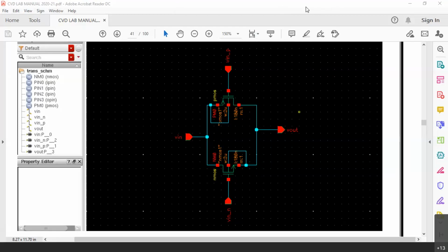Yeah, there is no power dissipation at all, because in a transmission gate there is no power supply at all. In the other ways there is power dissipation, and here it's not there. That is why this is better. In static CMOS there is dynamic power dissipation at least. In static CMOS there is no static power. Kuldeep has given the answer that there is no static power dissipation. Actually there is no power dissipation at all, neither static nor dynamic. Now in the case of inverter, let me try writing the inverter circuit.